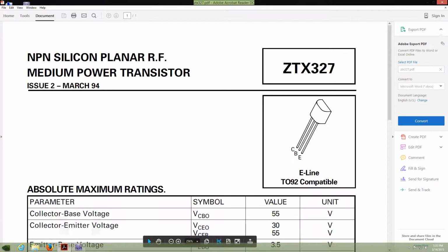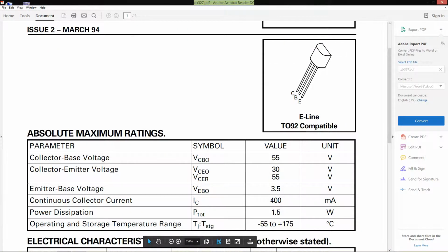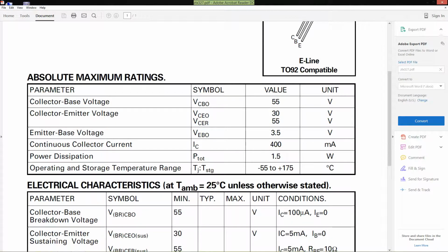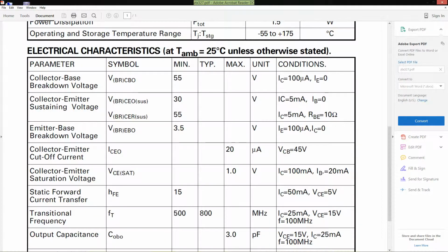Okay, we'll look at the transistor data sheet one more time and make sure the collector current is within limits. Then we'll place 2 voltage probes in and out so we can monitor the input and output voltage and see any voltage gain of the amplifier circuit.